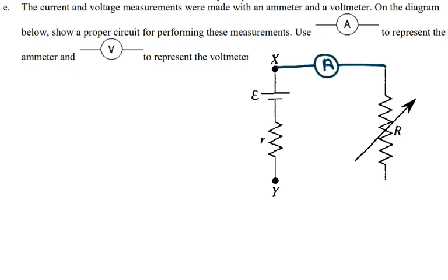And if you want to show voltmeter or voltage, that will measure the voltage between points X and Y. So if you want to measure the voltage between points X and Y, you have to plug it in anywhere between 2 lines. So I'm gonna plug it in right here. So you don't have to disconnect the circuit. You just plug in into these 2 points.